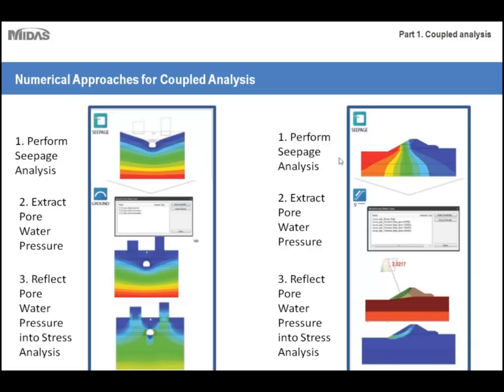Here we have another similar embankment type problem. Because there's water on this side of the embankment, the head is maximum at this side and minimum at this side, and you'll experience a significant amount of seepage on this side of the embankment. Using the program, you would run your seepage analysis, get your pore water pressure loads, and then import them directly into your slope stability analysis. You wouldn't even have to change your model file.